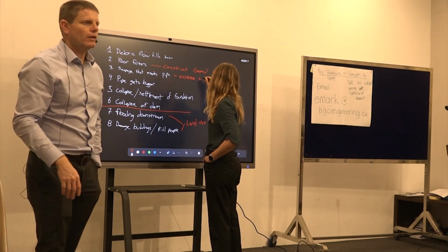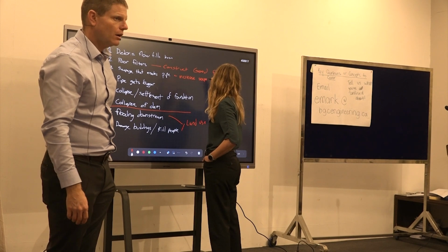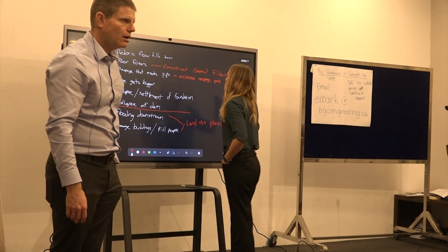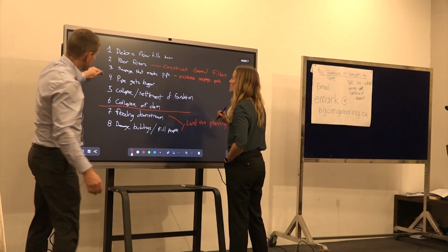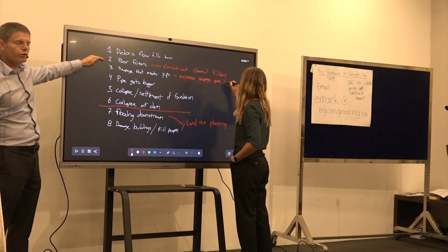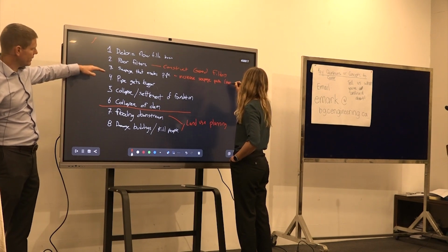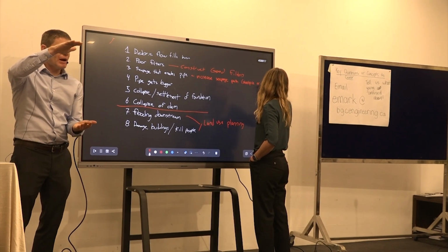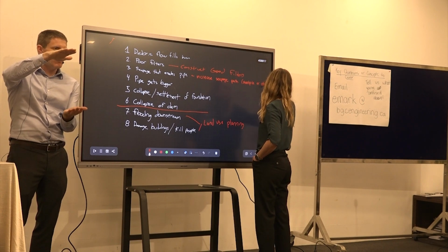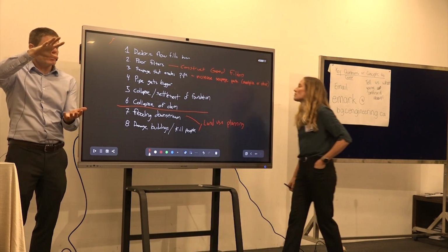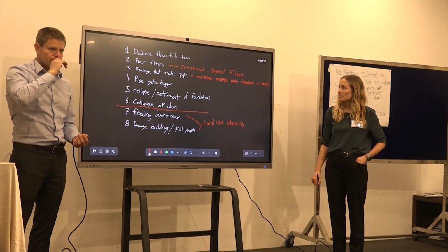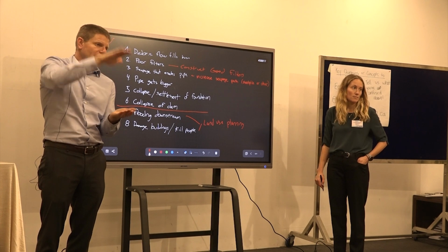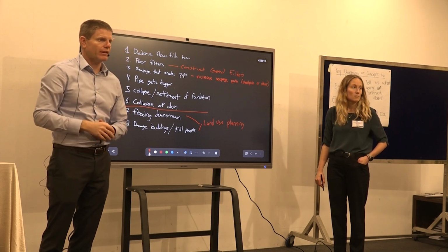So for points 3 and 4, I think we should decrease the water level by discharging it through gates and spillways. That's right. So it could be that our structure actually is controlled by this failure mode, right? That we realize that in the foundation there's a maximum amount of head, or a maximum height of the water behind the structure, and if it was larger than that, we could have seepage underneath. And so we can limit that seepage or limit that head by adjusting the height of the structure. That's what you were describing, I think, yeah?